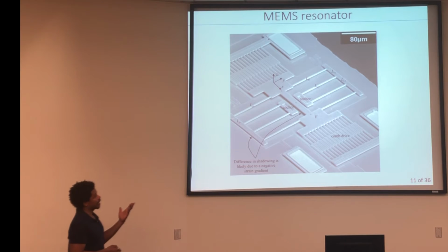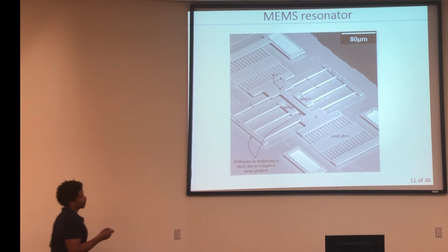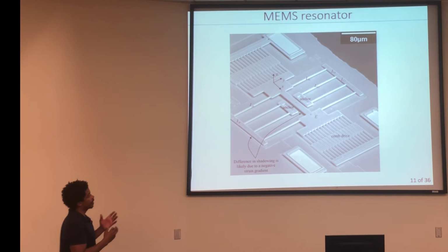The thing about compliant mechanisms is that even though it's all the same material, you're playing around with the compliance of the material, right? This is silicon, that's silicon. But this silicon is very thin, so it's very flexible. This silicon is very thick, so it's rigid. Or you're approximating it as rigid. Okay? So you're playing around with geometry, sizes, and the material properties to try to get things to behave the way you want.